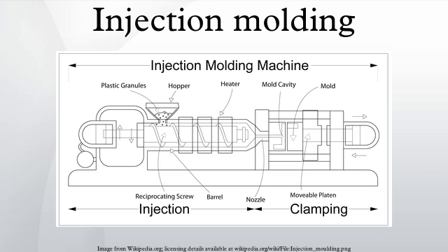More complex parts are formed using more complex molds. These may have sections called slides, that move into a cavity perpendicular to the draw direction, to form overhanging part features. When the mold is opened, the slides are pulled away from the plastic part by using stationary angle pins on the stationary mold half.